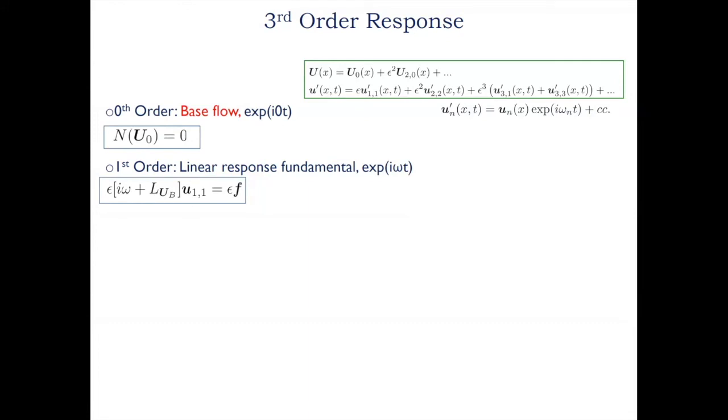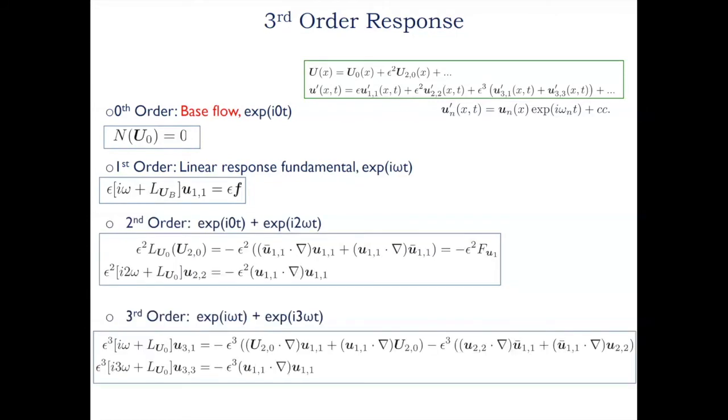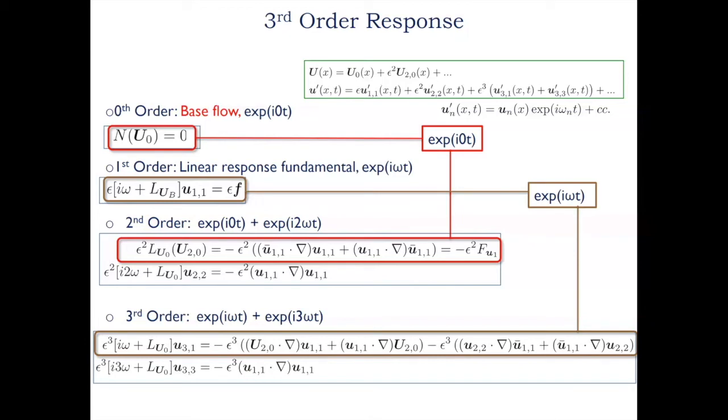One attempt, which is very natural, would be to try to use an asymptotic analysis. A naive expansion: you know that you have a small forcing F, so you expand at different orders. I will skip the details, they're not interesting, it's straightforward algebra. But a major problem appears: for epsilon small, your series is convergent, but very soon it's not convergent anymore. These are the results here. You see in red the DNS, direct numerical simulation, with the gain. And you see here the first order, which is linear. It assumes that nothing depends on epsilon, obviously, because it's a gain, so the response is proportional to the forcing.